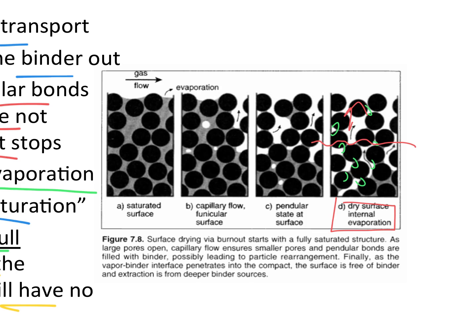You could, if it's heavy particles, the marbles will just start falling off the pile. You start to shed particles on the floor of the furnace because there's nothing holding them to the rest of the compact, whereas the interior might still have those capillary necks. So in a successful system, those capillary necks will be the same everywhere at the conclusion of that particular point in the process. Hopefully that makes sense.